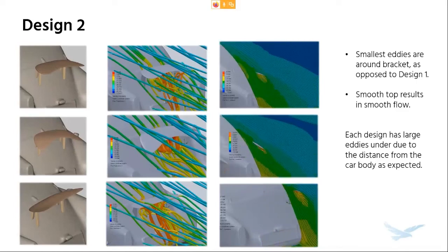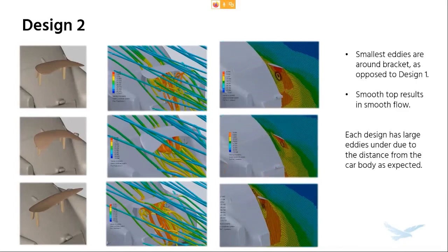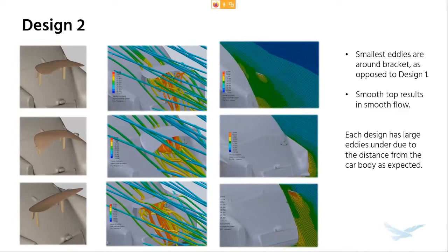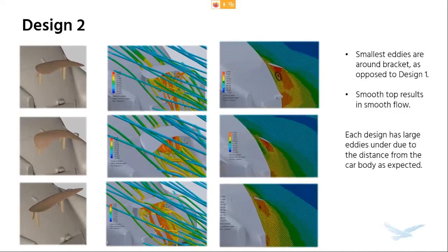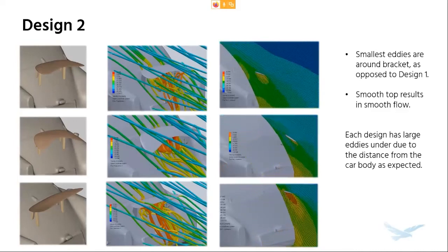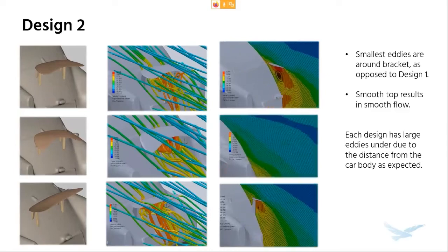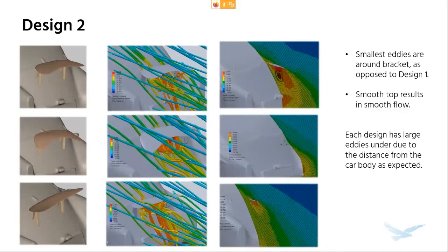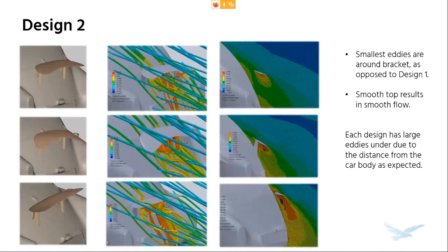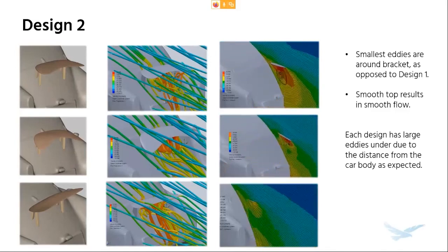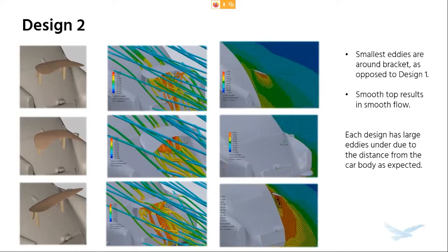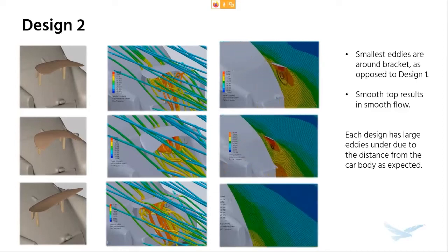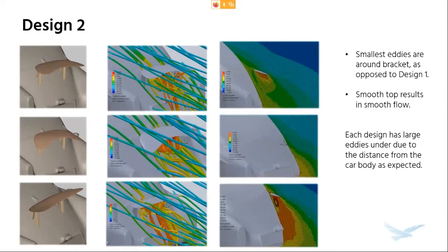And in this case, I found that having something, again, parallel or pointing straight with the car or the ground, and then something kind of tailing up, both cause some issues. We have those biggest eddies on those, whereas something that was actually kind of forming with the car, something pointing down, had very little eddies under it. You can see that the airflow kind of goes under, but a lot of traction starts happening just around the bottom part of the spoiler. So these are, again, factors I kept in mind.